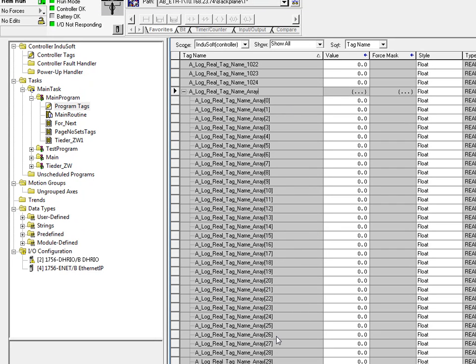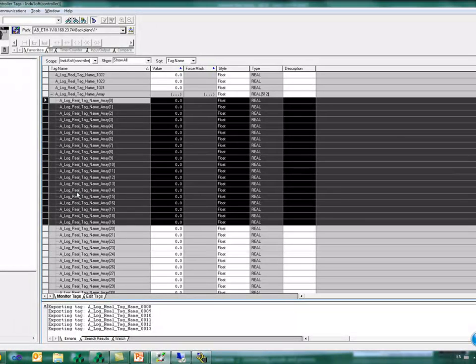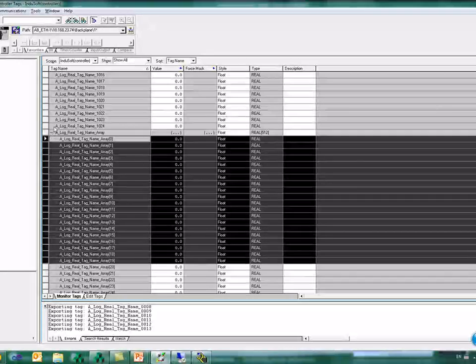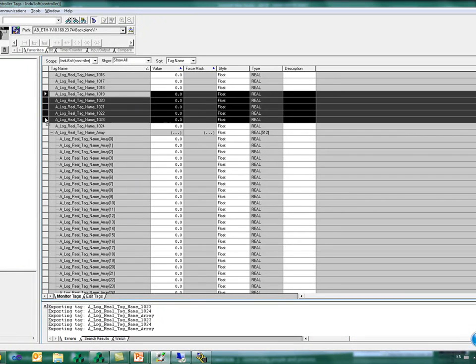Okay, because what I send to the PLC is the tag name, initial position, and number of array positions that I want to communicate with, and the PLC replies back only with the data. So again, this is going to be way faster communication than if you're doing something like this here, where each one of the tags has a different name. Okay?